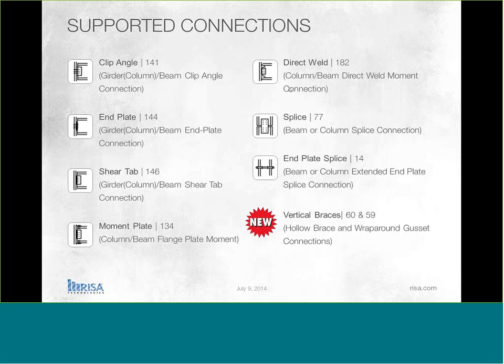Now, you'll see that we've got the description of the type of connection, the clip angle. Right next to that is the number of that parameter inside of Tekla. So Tekla Structures has a connection type 141, and that will be described as a clip angle inside of Tekla Structures. We'll see that in action coming up, and I'll demonstrate how to see that. But you can define your connections in Tekla Structures using these code numbers, 141, 144, and that would describe the type of clip angle or end plate that you'll be using.